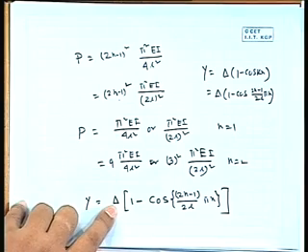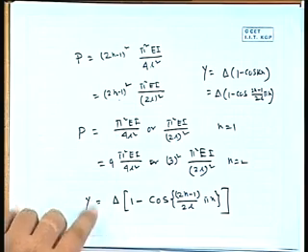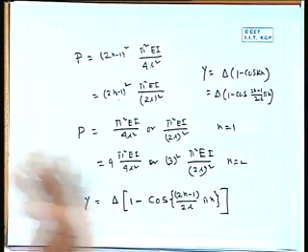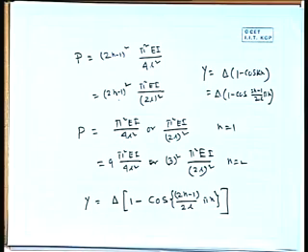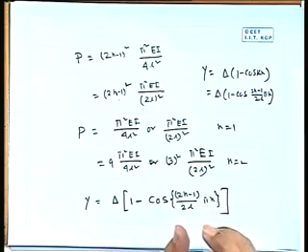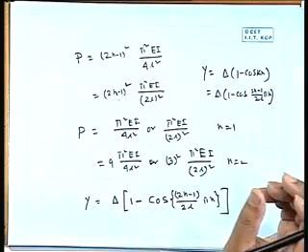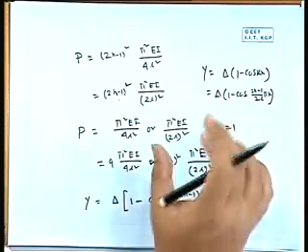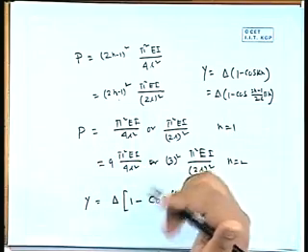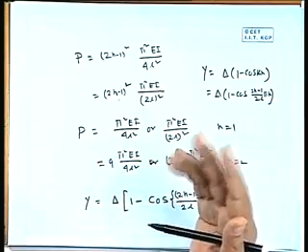It is dependent on your delta. So if you make it 1, you will get this shape. If it is 2, the shape will be identical, only magnified by a factor delta. And the P value will be pi square EI by 4L square multiplied by 1 or 9, or next time 25.